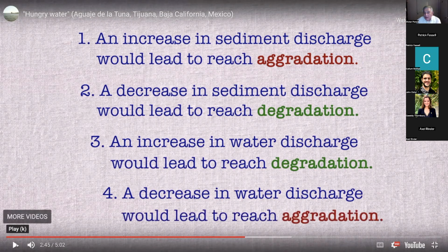So what is this aggradation thing? And the answer is under stable, steady conditions of water and sediment transport, there would be no aggradation or degradation. Aggradation and degradation are happening only when there's instability of the bed due to changes in water and or sediment transport. So aggradation has to be studied with modeling. Now we have models to do that for the last 30 or 40 years.